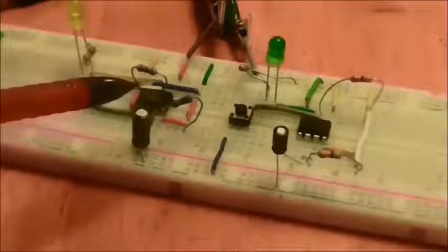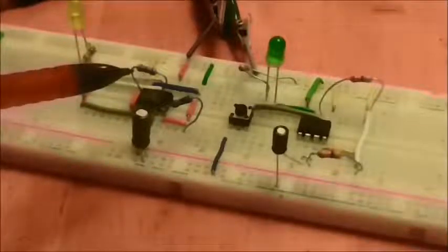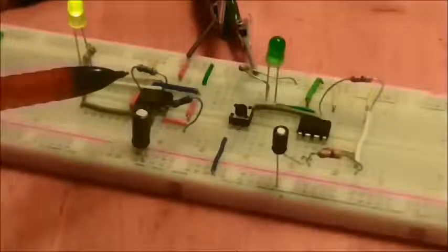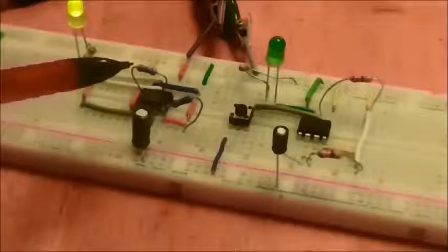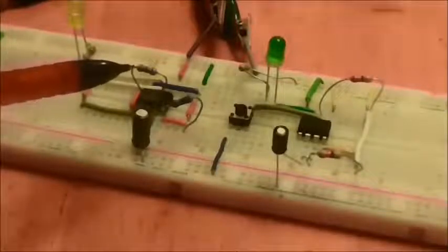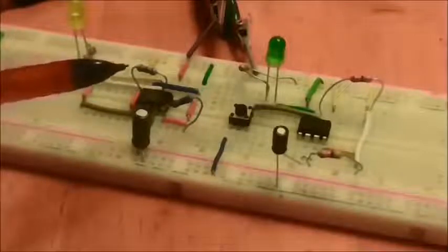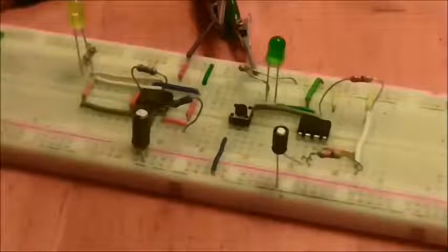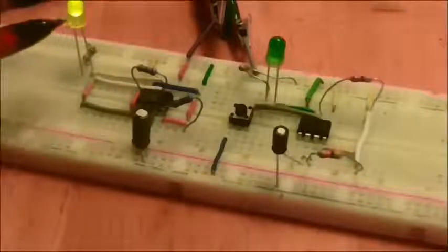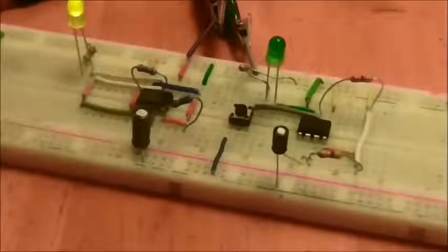And again, to find T2, we're doing 0.693 R2C1, and we've got 1 for R2C1, so we multiply by 0.693, and the answer we should come up with there is 0.693, and we'll call it 0.7 for roundness sake. Summing the two together gives us the whole duty cycle of this thing, and that should be 1.5 seconds.